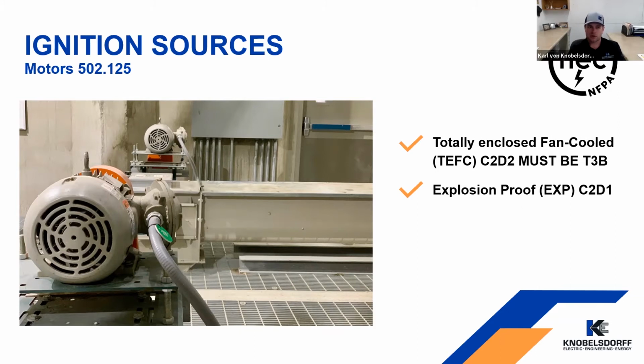So part of doing the initial hazardous classification study is to tell us what we can do. And we're always trying to make the areas as safe as possible and declassify everything that we can so that your facility is safer and you can use materials that don't have to be rated explosion proof or dust ignition proof. So for motors, motors are looked at under Article 502.